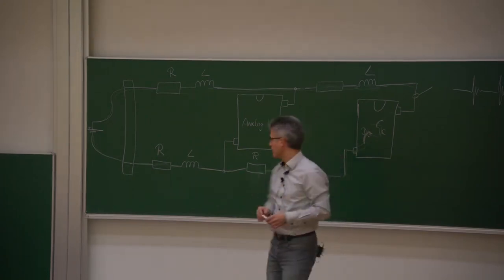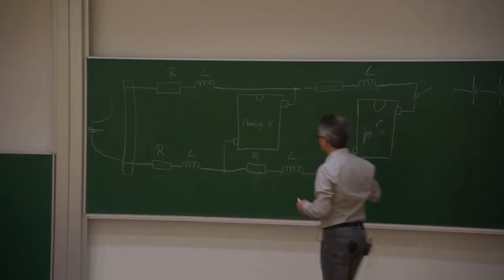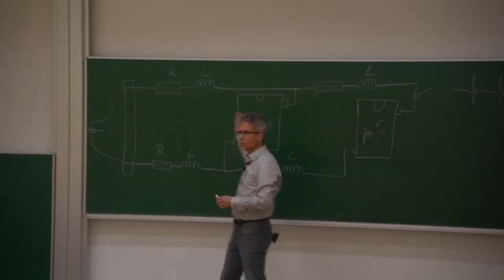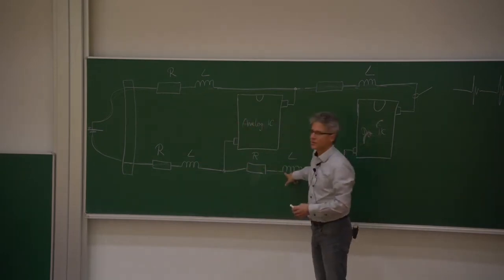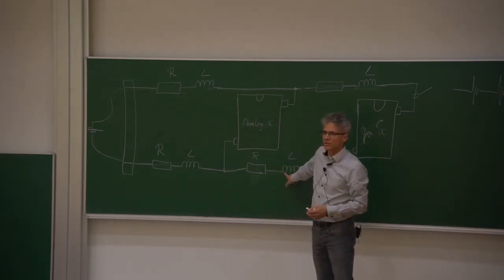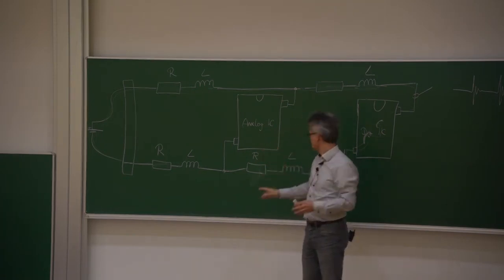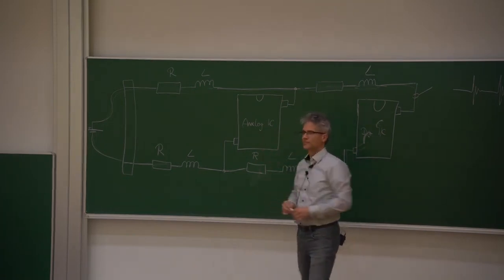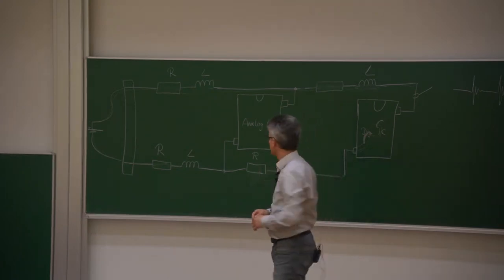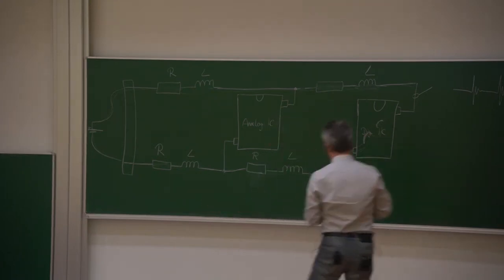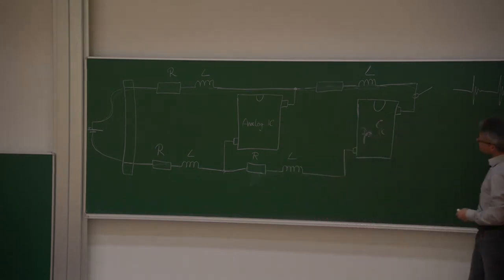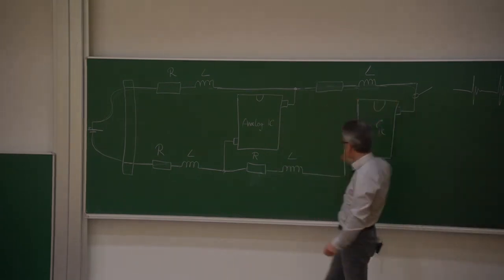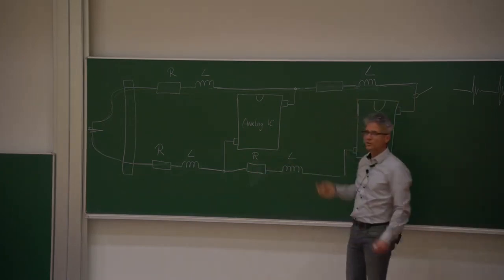Okay, just to clarify things. I hope you agree that if we have a very big loop, one fraction of the loop area can be related to a partial inductance that has some nanohenry. Okay, good. So what's the point? The point is we have these current spikes. They are now flowing in the loop area generated by the switching activity.